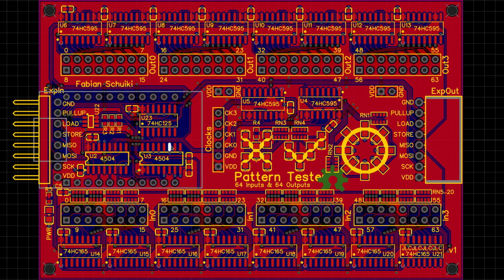So in a sense, the first byte that leaves the Adafruit, the first byte we shift out, is the one that's going to move the furthest away to the right in this whole chain. And complementary to that, the last byte we shift out here is the one that's going to end up right here in the leftmost shift register and correspond to our leftmost data.